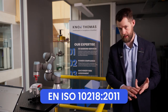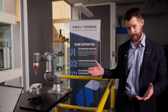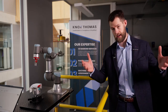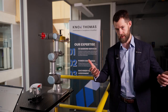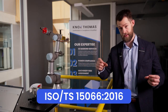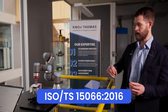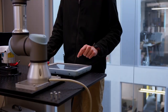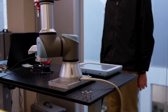Now, one of the requirements in there is a risk assessment being completed, obviously identifying the hazards and then identifying appropriate control measures. The question then is how do you validate that you have suitably implemented those control measures? So within your risk assessment, you'll have identified using 15066 to look at load and force limits. You'll have identified, am I going to put my hand in here? Okay. If I am going to put my hand in here, what is the appropriate load that the cobot can then apply to my hand and it be deemed safe?